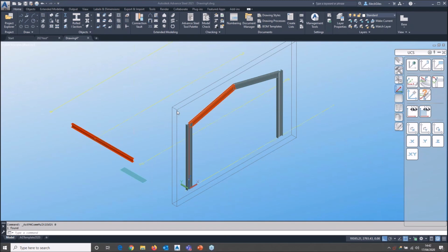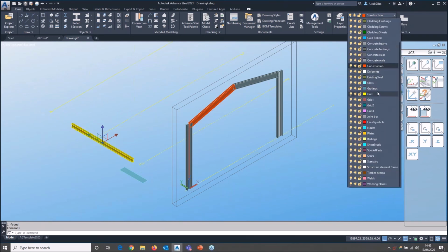You should never model in a glass layer, correct? Yeah, you always stay on the layer called standard. Make sure that's the current active layer at all times. And then after you've modeled the glass items, I would just select them and change the layer to glass. So as long as you change the layer after you've selected something, I can select that beam, and then I change the layer, whatever layer I pick in the drop down, it will go to that layer.